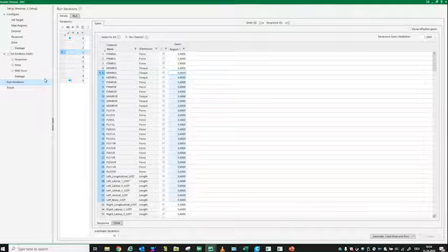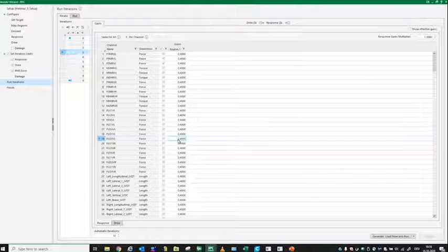Can you change the model with the iteration scheduler? The question should be more precise. Maybe you're referring to Turbo, which adapts the inverse, of course, and these gains here are not adapting on their own. If you have Turbo off, you will use the inverse FRF which you measured, and these gains will be applied. So it's still the same process, the gains multiplied with the inverse to get your drive estimate for the next step. This will stay the same.